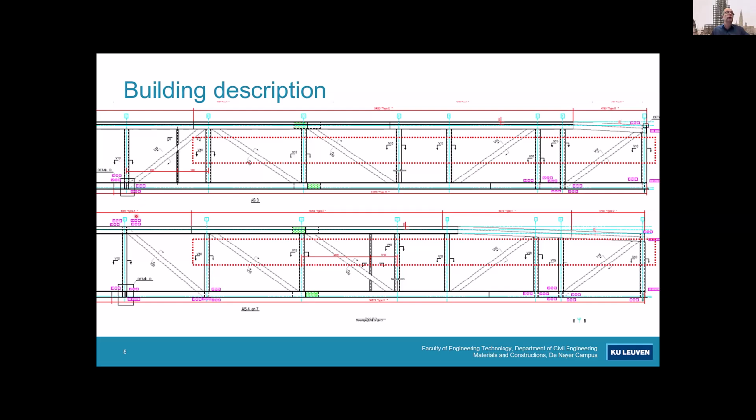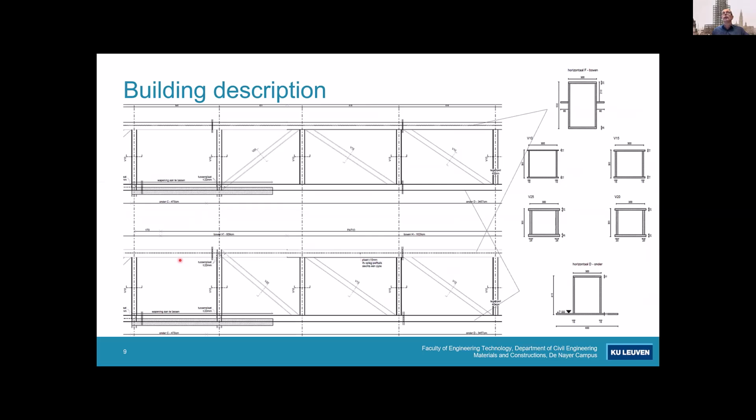So there is something going on. Also here, I see that my rectangle is not going far enough, but you see that the most loaded vertical studs have the basic thickness, and it seems not to be logical at all. Again, this is the same, and now you see the cross sections, how they are composed. So you see that the upper part is a horizontal beam with two lips on the side. Then you see that the studs, the vertical ones and the diagonals, by the way, also are hollow sections which are composed out of plate of 10 millimeters, 50 millimeters, 20, 25.